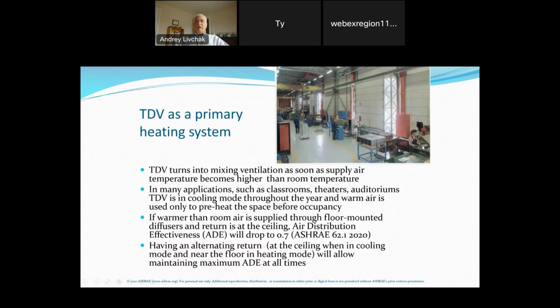Again, when you use a displacement diffuser to supply warm air, it will start rising into the upper part of the space. We conducted a comparison study in Finland, where, as you know, we have pretty cold conditions. We used two types of system. We used a mixing system, supplying air from the ceiling with nozzle type diffusers that blow warm air with high velocity into the occupied zone. Another option for heating was using a displacement diffuser, supplying air at low velocity into the occupied zone as well.